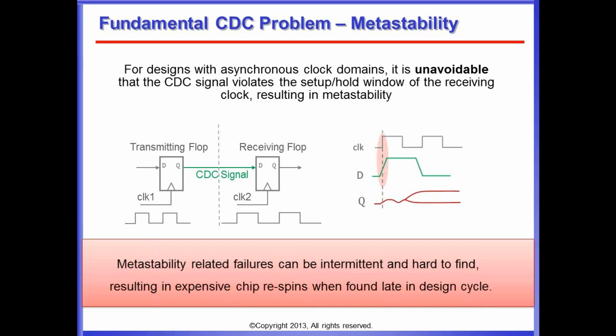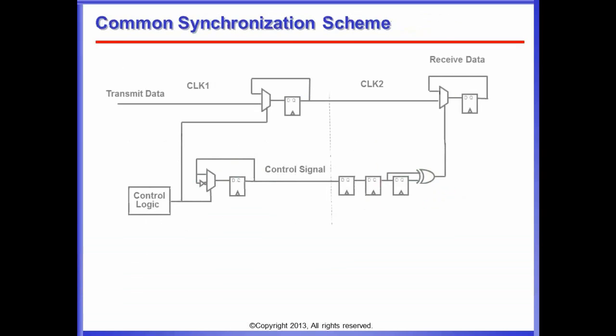This is not a problem for synchronous clock domain crossings, where you have well-defined and aligned edges, you know your timing, and you can verify this with traditional STA. But for asynchronous clock domain crossings you need some kind of add-on or additional analysis. In the previous case you could simply add another flip-flop after the first receiving flop to overcome the time until the flop swings in.